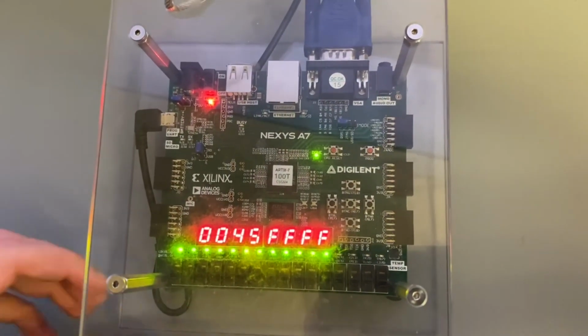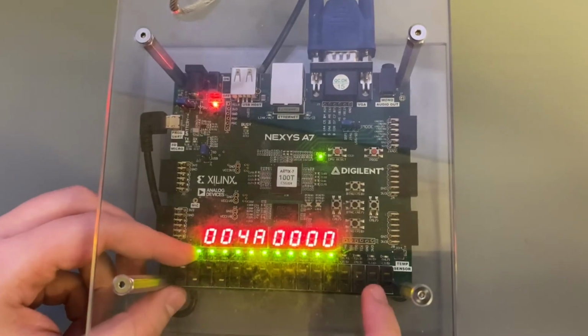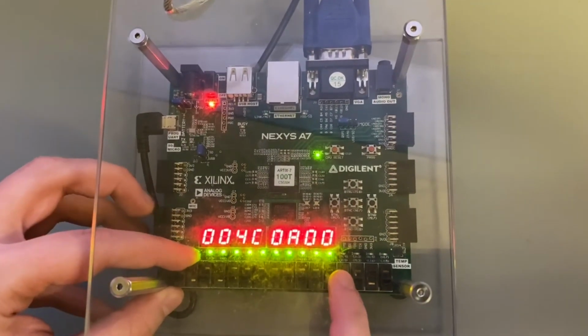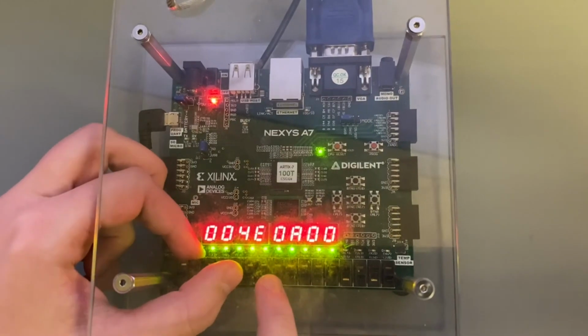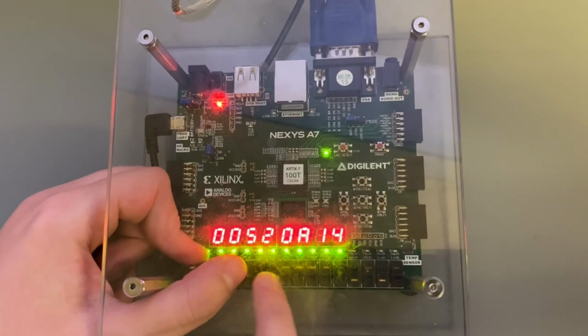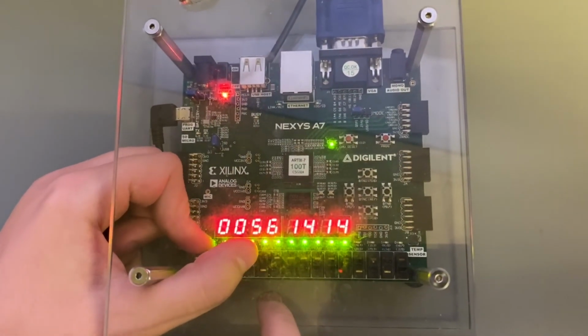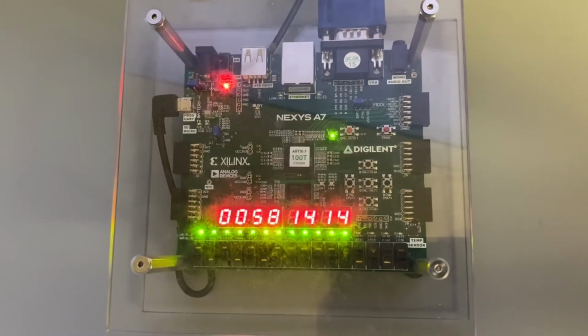So at this part, we're just testing our 16-bit adder to make sure it properly adds. We're flipping the mode to mode 5, which is the adding one. And now I'm flipping through each A, B, most significant, least significant, to make sure it properly adds and gets the proper result of 1414 in hex.